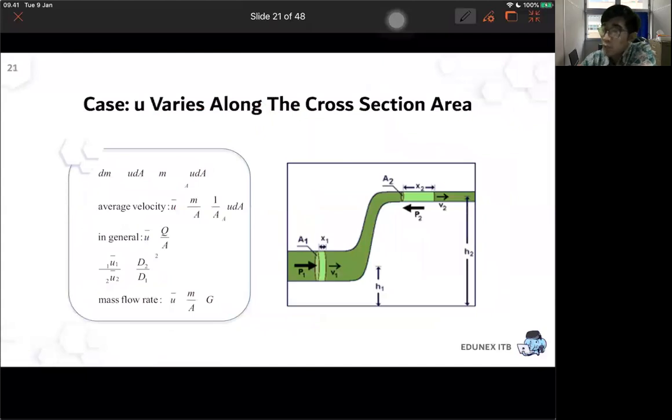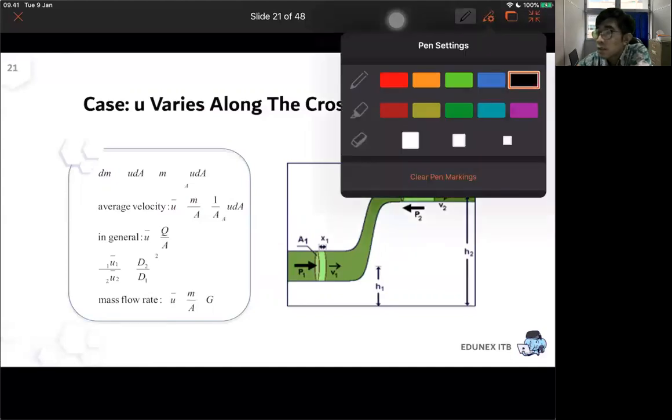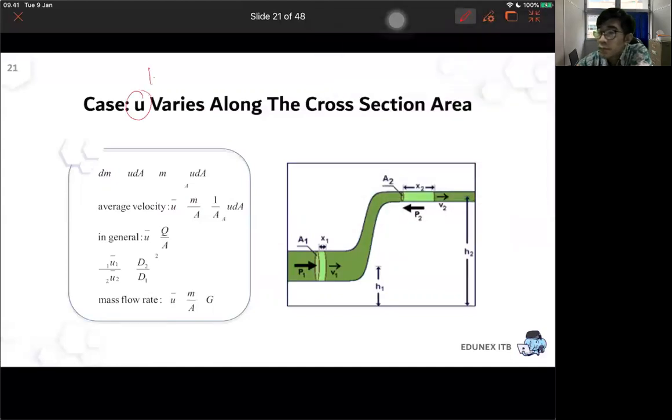You do not need to be confused by the equation, some symbols are missing. But if during the travel the pipe is changing in terms of cross-sectional area, it means the size of the pipe is changing. It means the linear velocity will also vary.